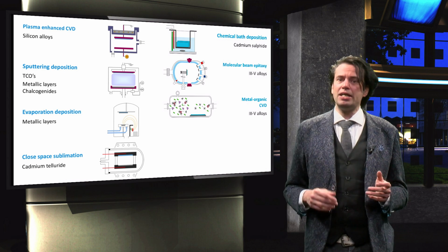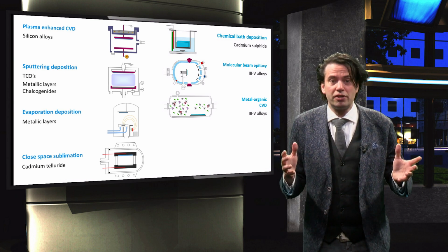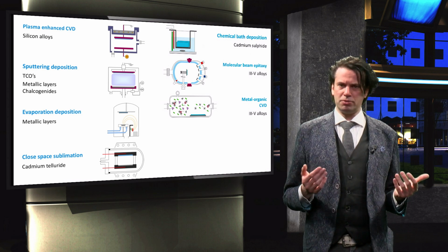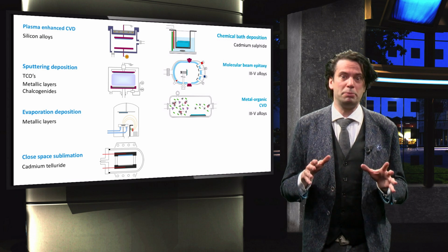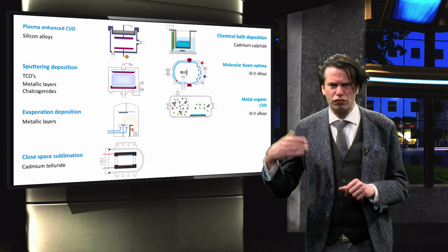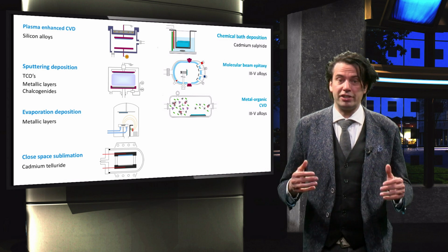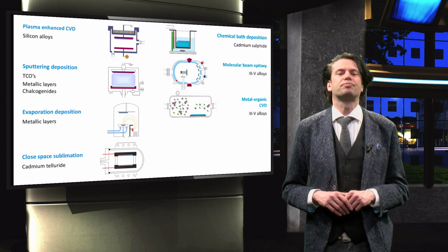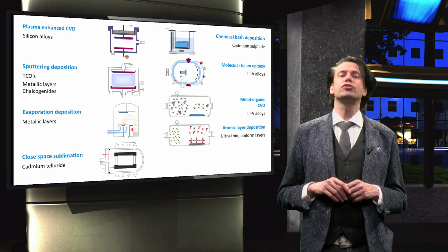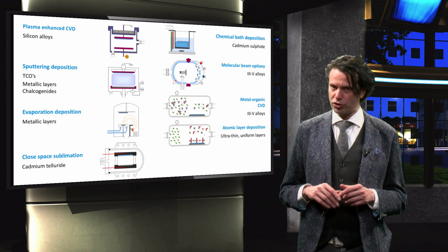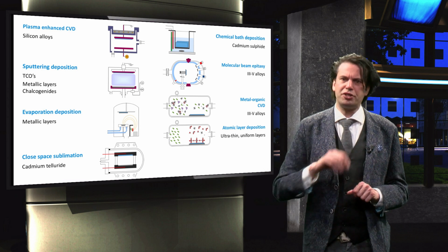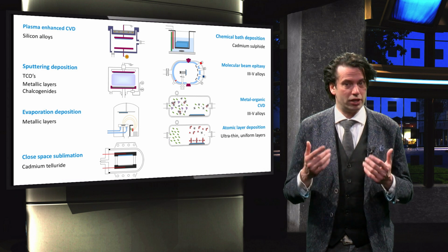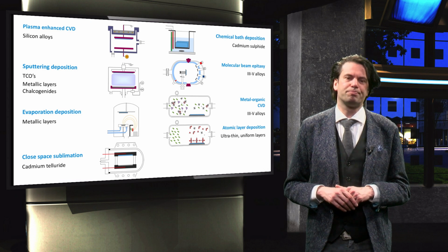In reference to MBE, MOCVD is cheaper, has a higher deposition rate and results in lower purity of the deposited alloy. For MOCVD, target atoms are bound to 3 hydrogen atoms or methyl groups and are passed in gaseous form over a heated substrate. The elevated substrate temperature dissociates the precursor gas and a thin film of target material grows on the substrate. Atomic layer deposition involves a series of sequential alternating flows of precursor gases that react with the substrate. ALD produces very uniform layers, even at very small thickness, but can be a relatively slow deposition technique.